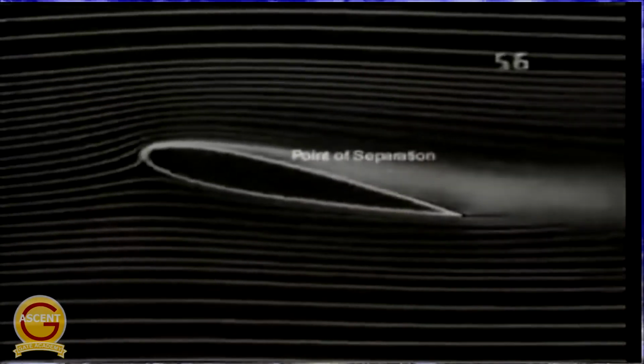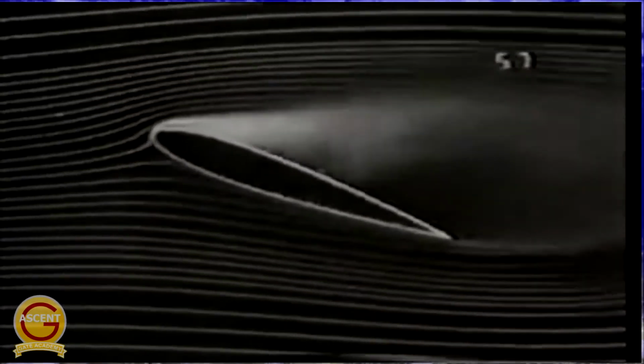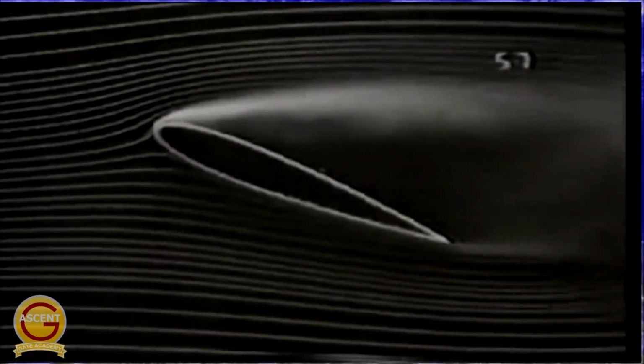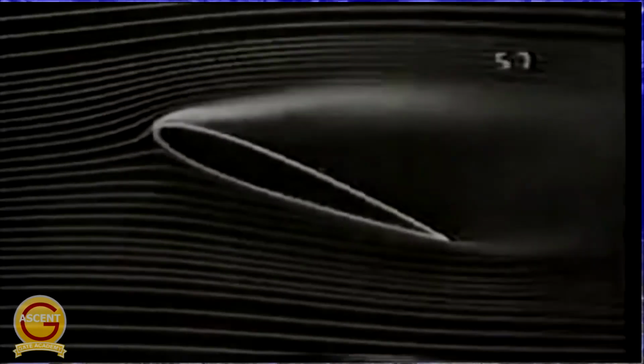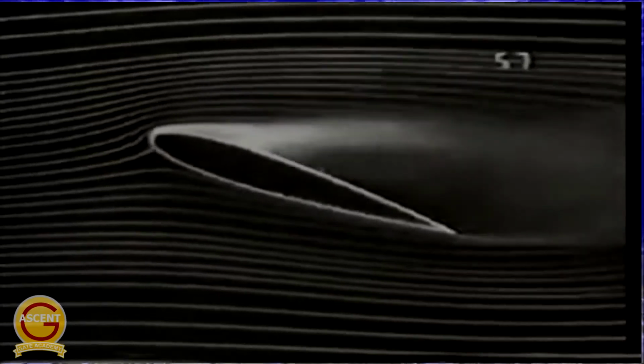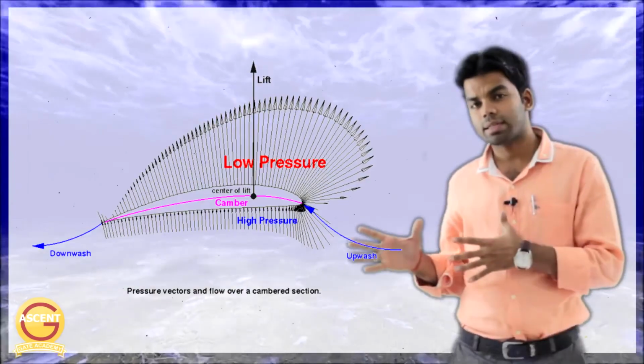Initially, as the angle of attack increases, the lift will increase, but after a certain point, as the angle of attack increases, the boundary layer separation starts shifting towards the front edge of the airfoil, and lift starts diminishing. The point after which the lift starts diminishing is called the stall point, and the angle at which we get the maximum lift is called the stalling angle. Beyond the stalling point, since the boundary layer separation is shifting forward, there will be wake formation at the back, and because of this wake formation there will be more and more drag force.